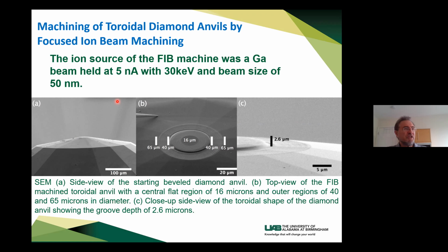Yeah, and one more comment concerning diamond. When you analyze maximum strength, you mostly use linear approximation, so it's first order or second order elastic constants. In reality, from first principle simulation, we now know, not well, but up to fourth order elastic constants, which includes pressure dependence. And actually, it's possible to analyze with finite element, and we did this in more detail, the stress strain state of anvil and sample and gasket also, and also some equivalent stresses.